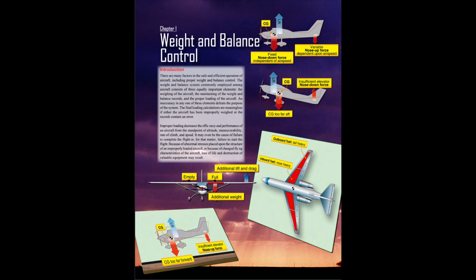Improper loading decreases the efficiency and performance of an aircraft from the standpoint of altitude, maneuverability, rate of climb, and speed. It may even be the cause of failure to complete the flight or, for that matter, failure to start the flight because of abnormal stresses placed upon the structure of an improperly loaded aircraft, or because of changed flying characteristics of the aircraft. Loss of life and destruction of valuable equipment may result. End of page 1-1.